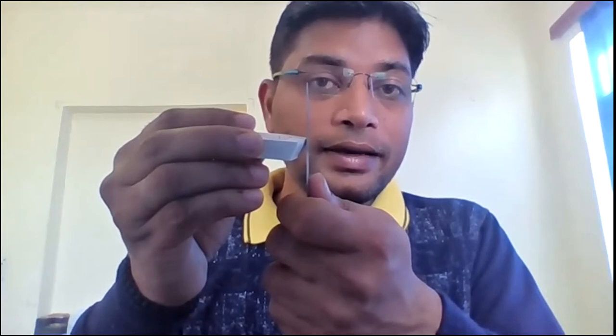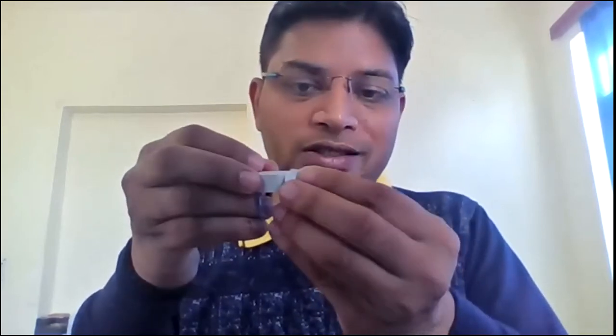This angle created is the end clearance angle. Because if we were not supposed to provide this clearance, then the complete surface of this material would come in contact with the workpiece. So to provide clearance, so that the material can be easily removed from the workpiece area, and so that the edge is created, we have removed this material. That's why we call it a clearance angle. Whatever angle is created on this side, we call a side clearance angle, and from this end portion, the angle we created, we call the end clearance angle.